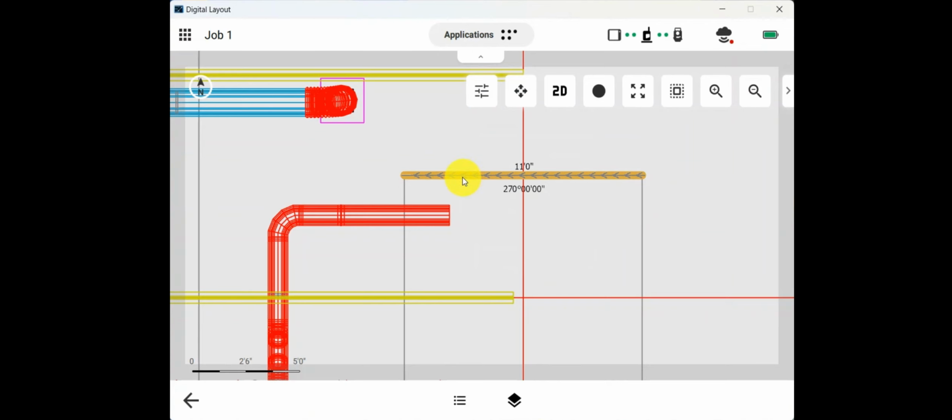So when you first open a file, just go around, tap a few lines, make sure that the scale is making sense, then start making points. If you make points on a file that's not the scale, you're going to have to redo all your points and re-import the AutoCAD file.